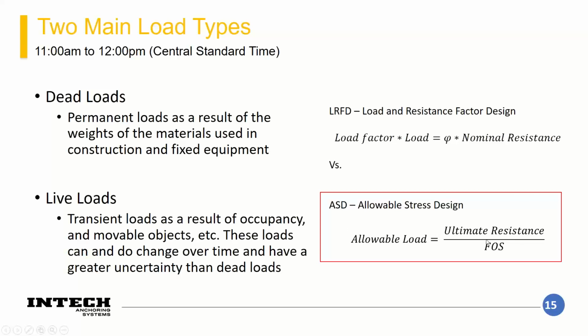The reason we do this for geotechnical design is that when we look at load and resistance factor design, it is actually more precise than the ASD approach. But it is useful in steel design because we know with a high degree of certainty what the resistance of the material is. If you're looking at a steel beam, you're pretty certain that it's going to have the strength that you need. But when you're talking about soils, this resistance factor is basically taking into account those uncertainties.